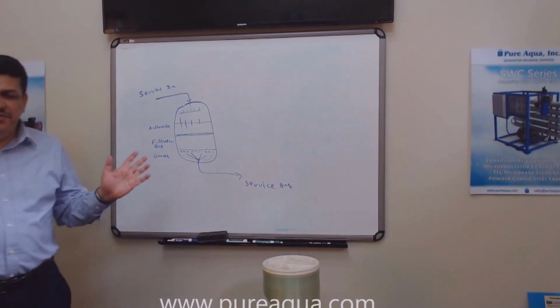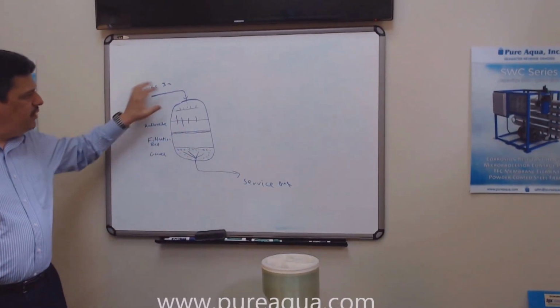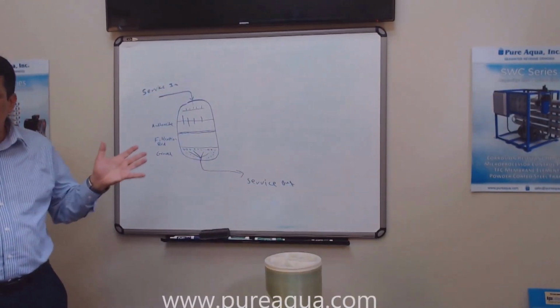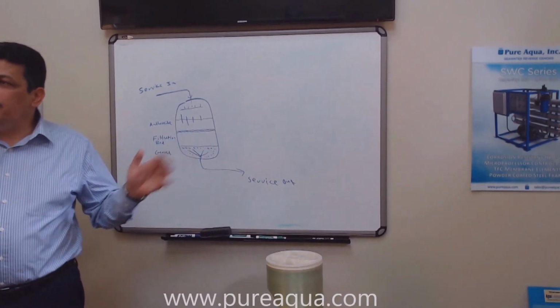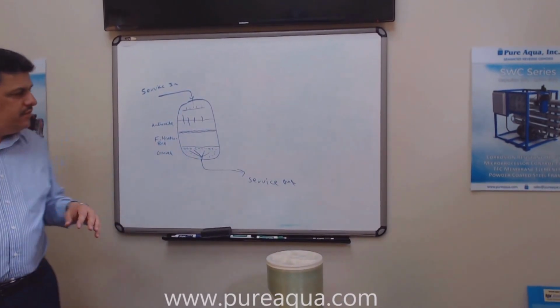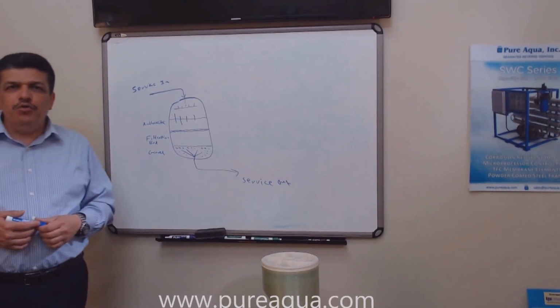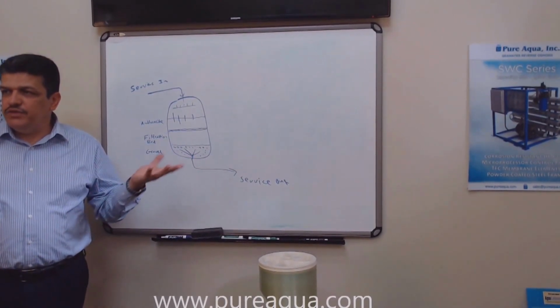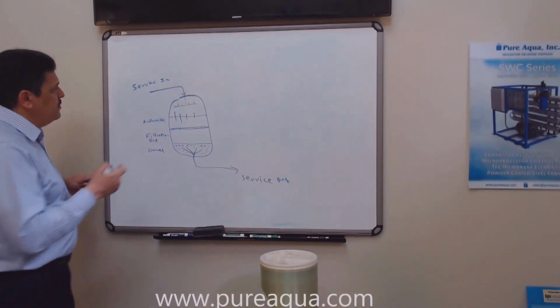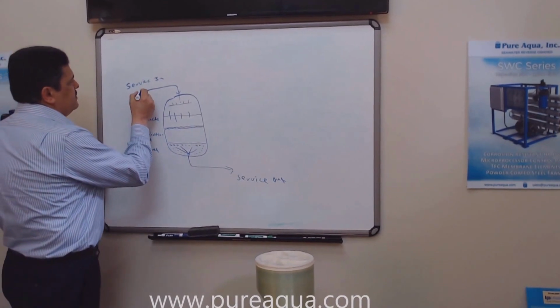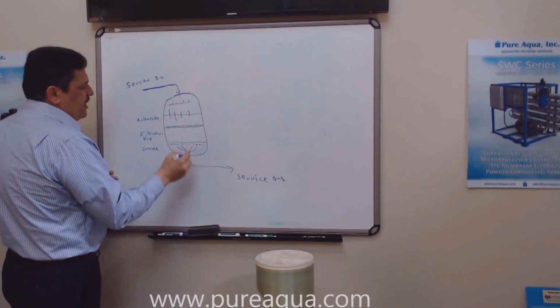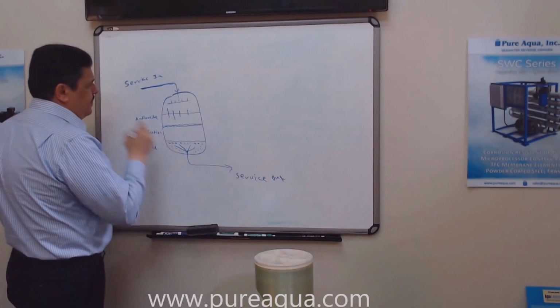Okay, so again, anthracite is an activated carbon filtration bed, and the different layers we draw. Now, you can ask me a question. After a few hours or after 2-3 days, depending on how turbid the water is, how are we going to clean it? So simple. When we say it's an automatic media filter, regardless of what's in the media inside, we have the service in like this, and we have the service out like this.